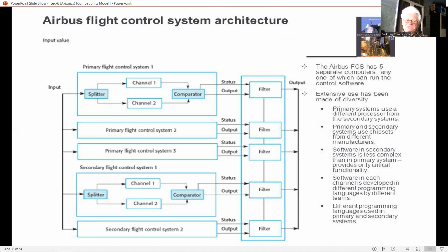A monitor triplet configuration comprises three totally independent parallel channels, with each channel monitored by a dissimilar system to detect a failure. Provided this monitoring is to a sufficiently high degree of integrity and confidence level, such a system can survive two failures.